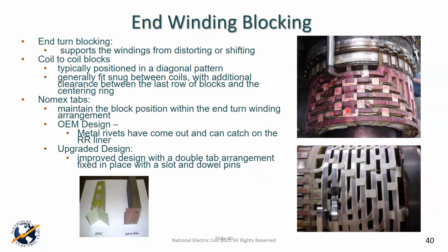All right, there's some connections coil to coil here as we look. And this is an unusual design. There's only a few of these left, but back during the war, aluminum was used as a conductor because copper was needed for the war effort. And there are still what they call Condal, or aluminum, rotors out there in operation. Not many of them. Most of them are in coal-fired plants, so their days are kind of numbered, to be quite frank with you. But it's interesting right here.